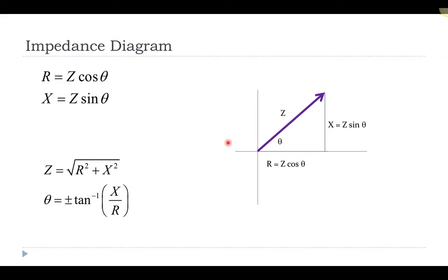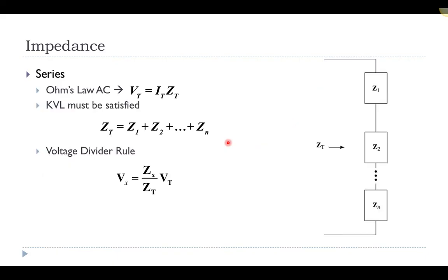And we're going to analyze circuits that are a little bit more complex, but just using the techniques that we've used in the past for analyzing circuits that are in series and parallel for resistors. We remember that in terms of series connections, the impedance adds together, so the total equivalent impedance of components that are connected in series just adds together. The current through all those components has to be the same, but the voltage would be different if the impedance values were different. Of course, we can always use Ohm's law